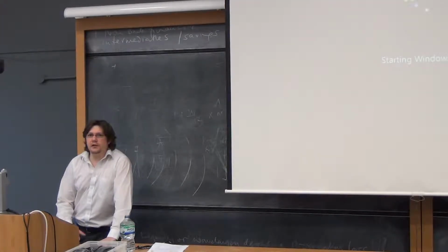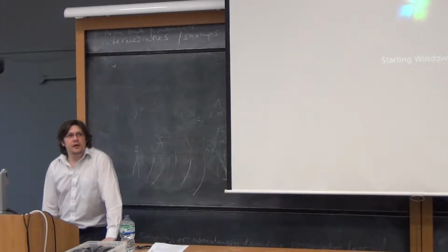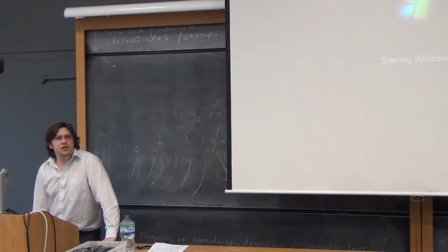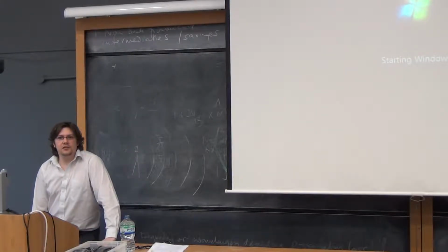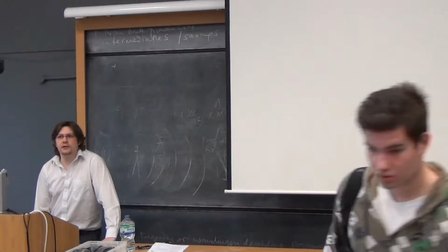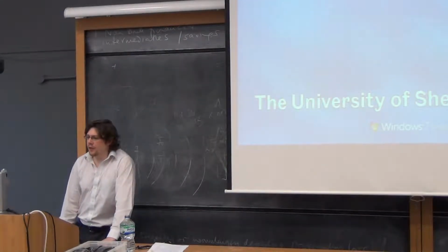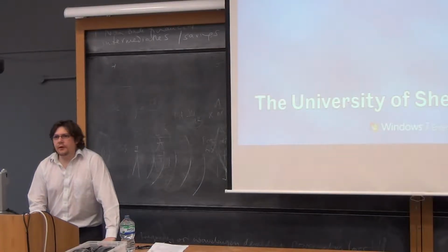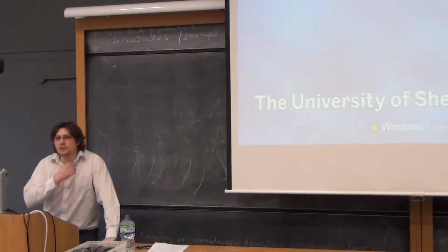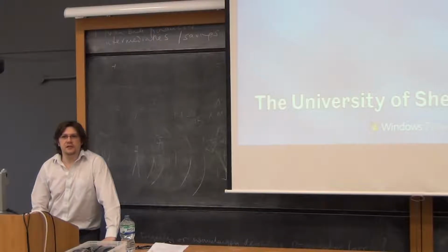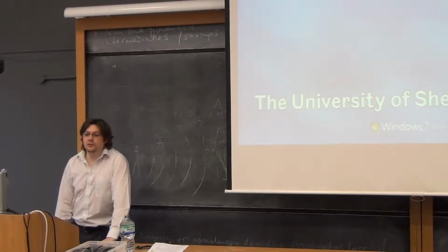The situation for the transistor switched on is both junctions forward biased, so the base is the highest potential electrode in the system, and the collector and emitter are quite close together. We also had a large signal model for a transistor that's switched off, and that's 2 open circuits with no diodes switched on at all.